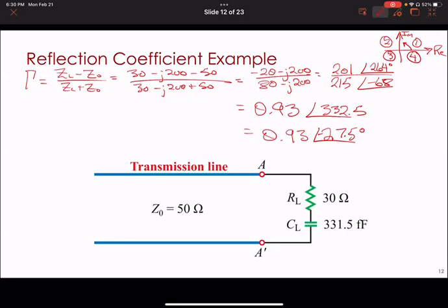You want that to be a low number, because you can imagine if you have a transmission line and you connected an antenna to the end of it, and you send a wave down this transmission line and not very much bounces back. In other words, you have a really small V0 minus. Not very much bounces back. It had to be radiated. Where else could it go, right? Now, if you had a lossy antenna, it could go into losses in the antenna. But if you assume for the time being that it's just a metal antenna, there's not much loss, a low reflection coefficient means the power's been radiated.